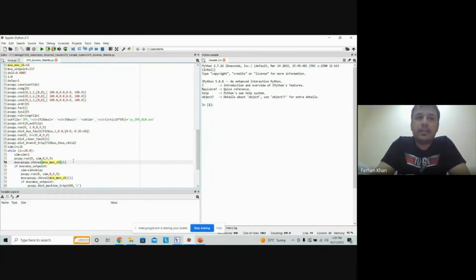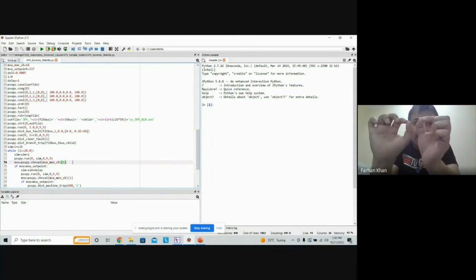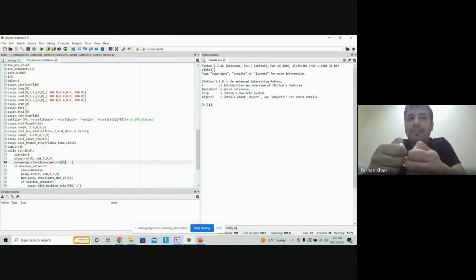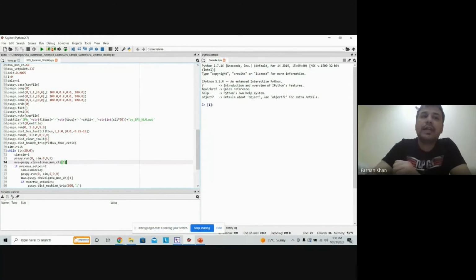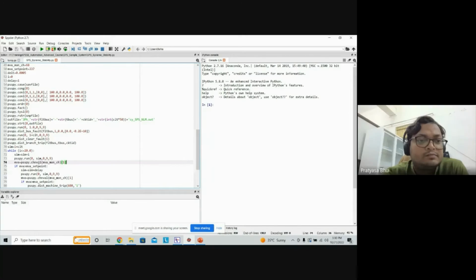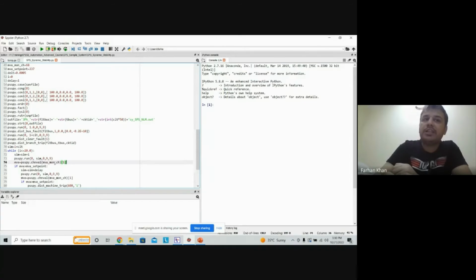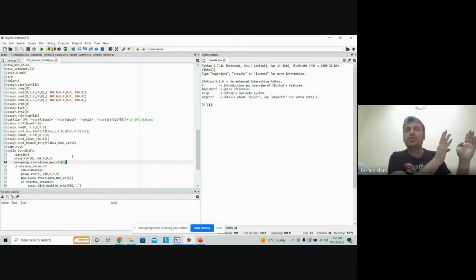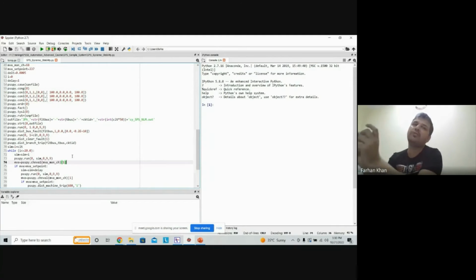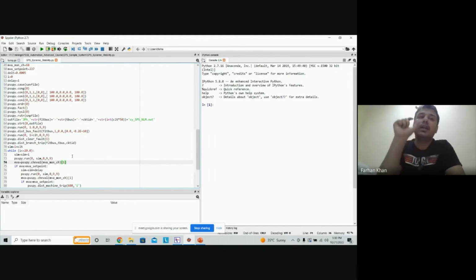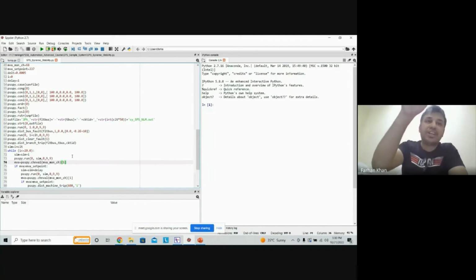This particular API within PSSE can be used to get the value at that particular instant in dynamics. So what I'm doing is psspy.chnval. This is going to give me the channel value, and MVA monitor channel. So this is the channel; in my case, this channel number was 68. In your case, whatever this channel is, it is going to come here. Index 0 is going to contain the time step and index 1 is going to contain the actual value at that particular instant. So I am getting the value of the channel, MVA, at sim or t equal to 1.1.